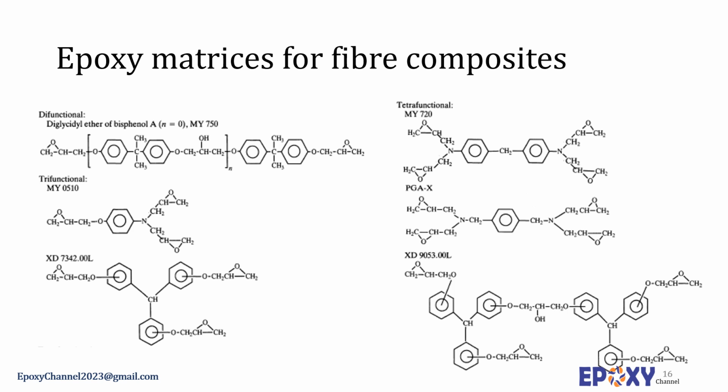The main types of thermoset in composites are epoxy and unsaturated resins such as polyester or vinyl ester. The epoxies are generally of relatively low molecular weight and satisfy the requirements of an appropriate matrix for composites, which are low viscosity for fiber impregnation, high reactivity and curing, no volatile formation, and yielding good mechanical properties of the